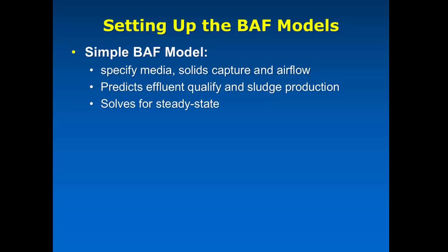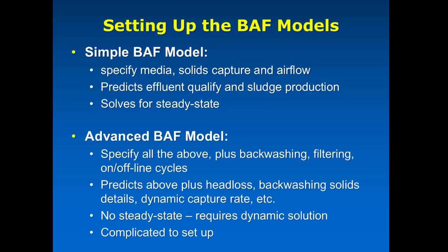The advanced BAF model, basically you specify all of that, plus there's quite a lot of detail there about the operation. How many units do you have in service at any time? How many are being backwashed? And how many are in filter mode and so on. And they have different things for taking things on and offline as it rotates around.